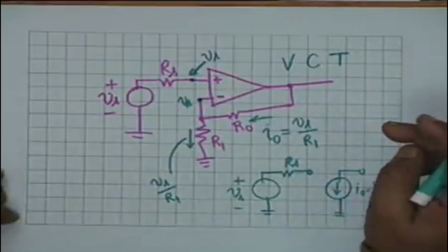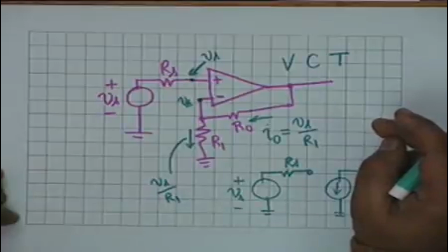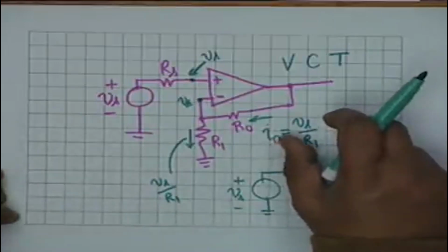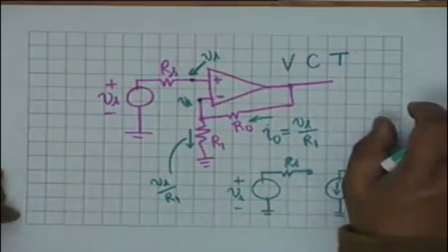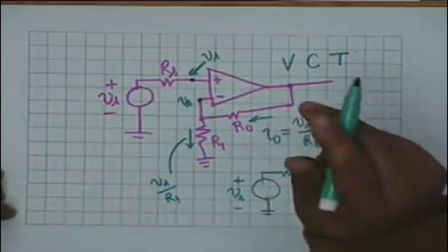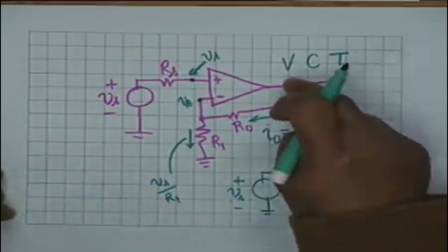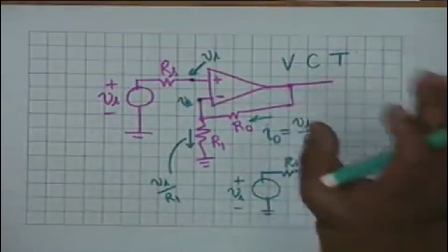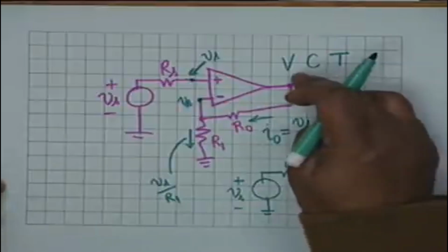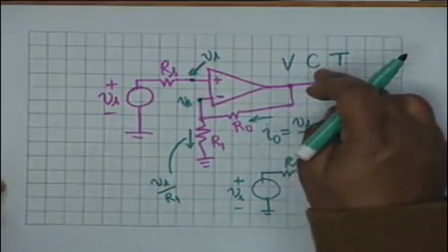A transducer converts a physical quantity into another physical quantity. For example, force could be converted to a voltage. The device that is used is a transducer. A voltage is converted to a current, both electrical quantities, but the nature of the quantities is different. One is an across variable, the other is a through variable.